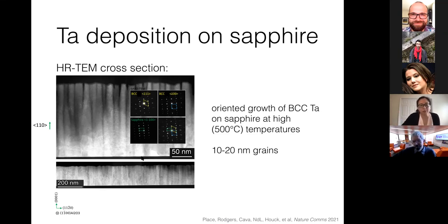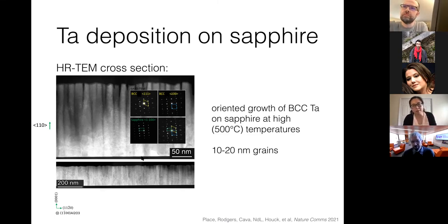So one of the things that we're currently working on really actively is trying to change this microstructure and see what impact that has on resonators and qubits. You can write down predictions that go in either direction. Naively, you'd expect the grain boundaries to hurt because they house two-level systems. But then they might also help if they do things like trap quasi-particles. So my approach as the dumb experimentalist is just, let's make a bunch of films with different microstructure and just measure what we get. And we now have enough parameters that we can fit that maybe we can really learn something about what happens in these underlying films.